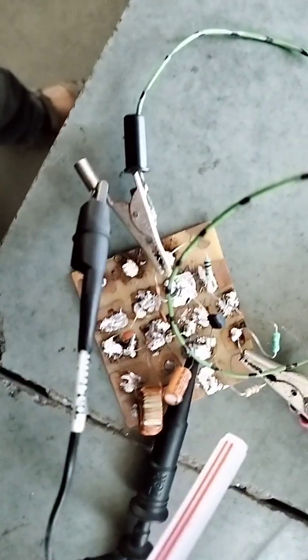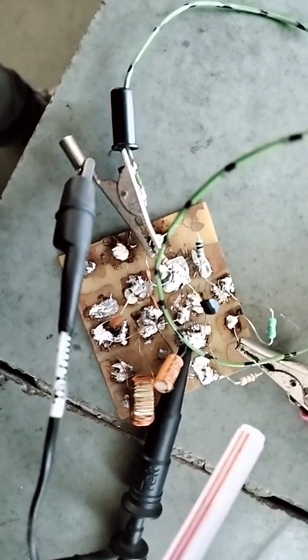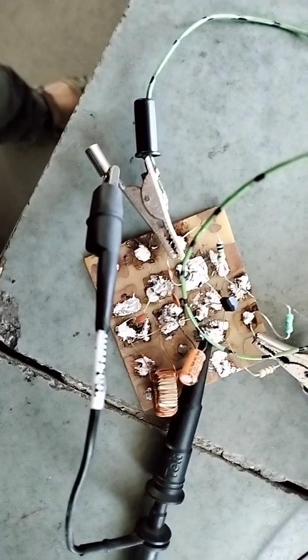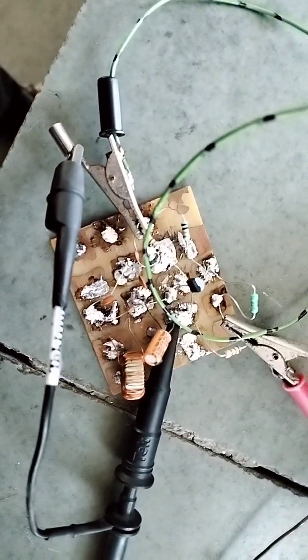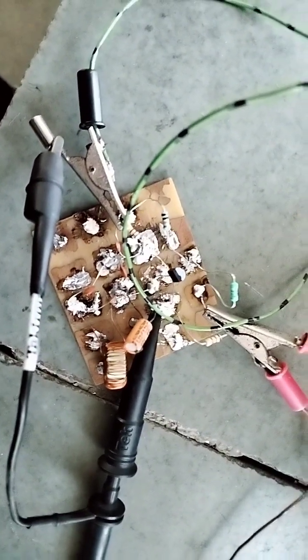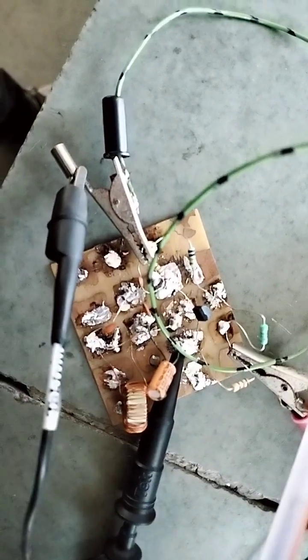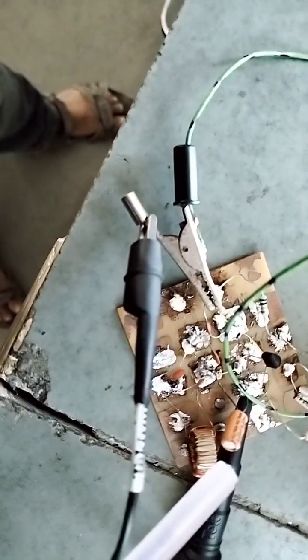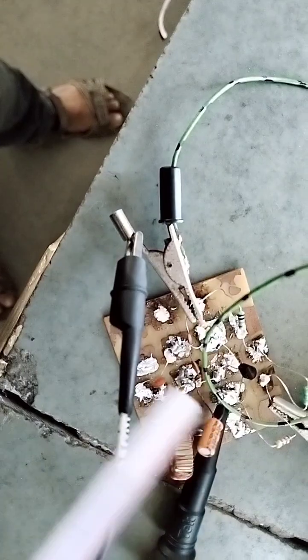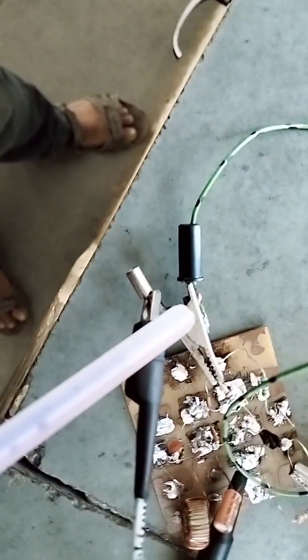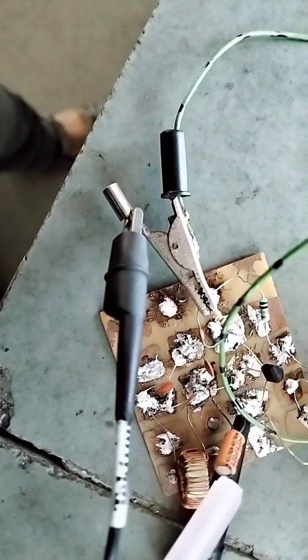Here I connected directly. You see I do not use any type of wire, because a wire works as an antenna, and if we make any type of circuit involving a capacitor, we always need to make it without any wires, right? So this is the resistor, this is a polar capacitor, the transistor, and all the resistors. This is my ground, connected with ground, and my signal is connected with a capacitor directly.